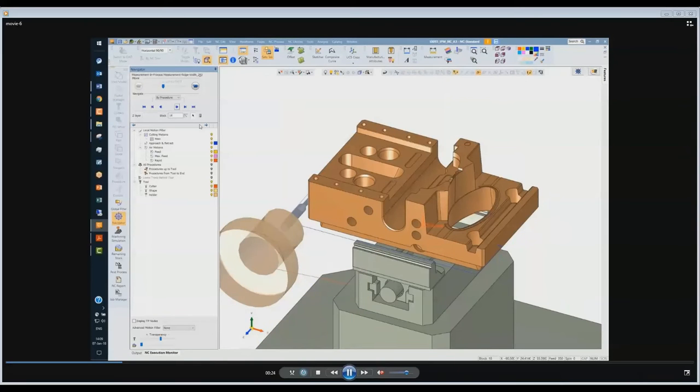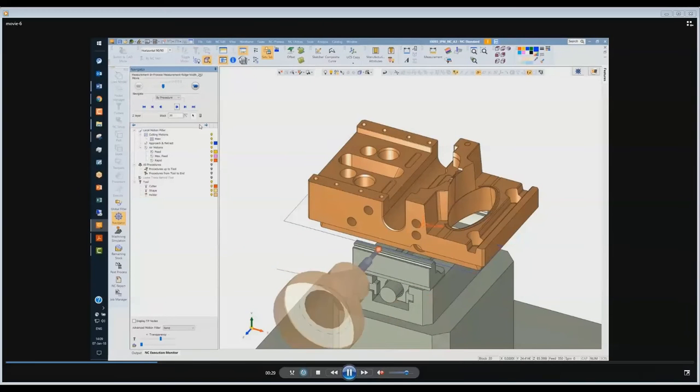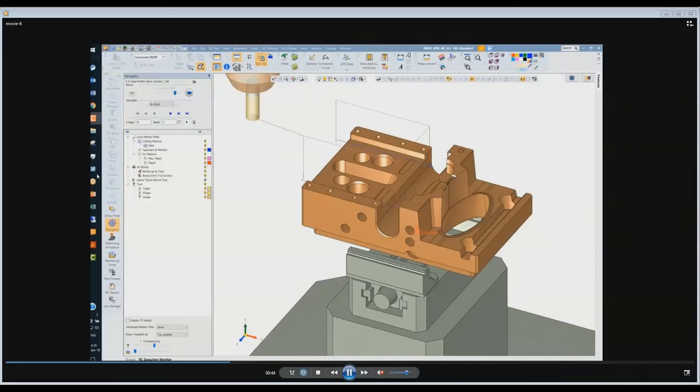Then we can measure the center of X and apply that, like G55, G54, X center, then Y center, and then measure a point on Z, and we have Z center.